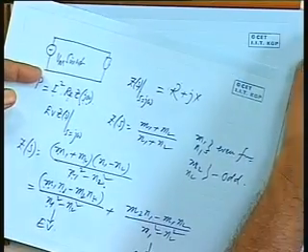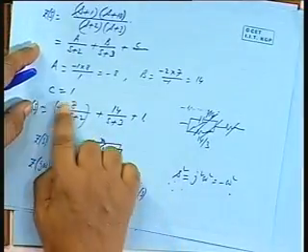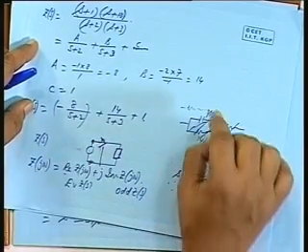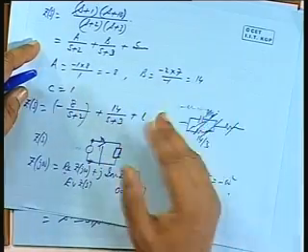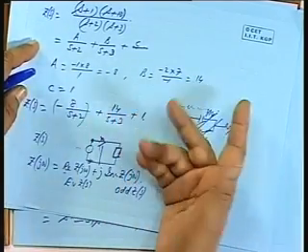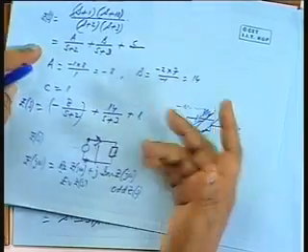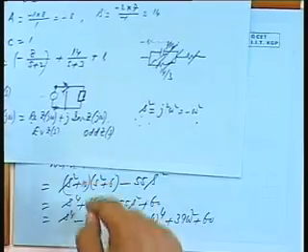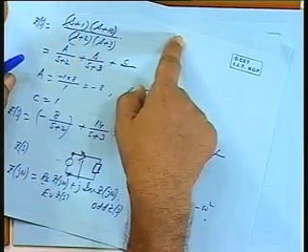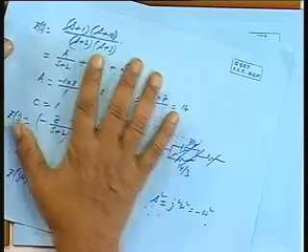So, even though we have seen earlier for this example that the residues are coming negative, it may not be possible to realize by RC combinations. You may try with LC, it may fail. It may be possible with RLC, all right. But it is a realizable function. So, if you find that this test fails, it is not positive throughout for all values of omega, somewhere it is becoming negative, then you can say it is not realizable by passive elements. This is not a network function.